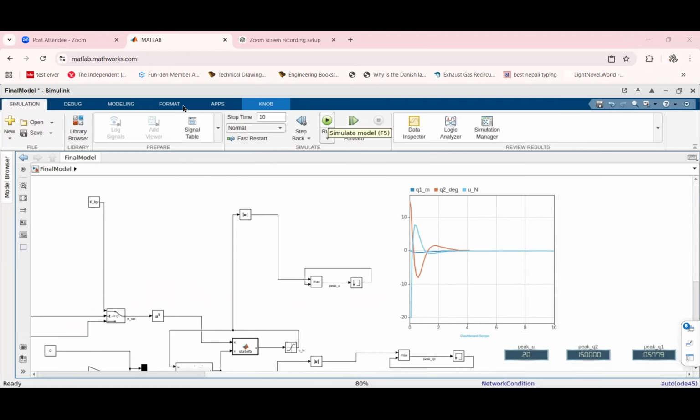What I can say is that LQR is preferred because it achieves stabilization with significantly lower control effort and smoother response, making it more practical and robust despite a slower settling time. If you are in an industry like robotics, we can go for pole placement.